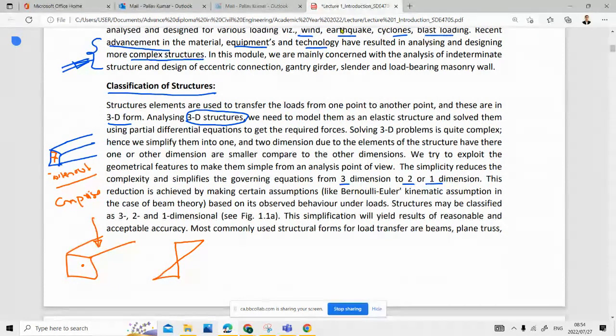Yeah, something like that. Yes, it's basically a stress diagram. Yes, it's an elastic stress diagram, and we assume that your material behaves in an elastic range. So that is what we do. And once we apply a load at the top, we assume that this form of shape will be there for the elastic stress. So the top will be in compression, because this is compressive stress, right? And the bottom will be in tensile stress. And if we talk about the central portion, we say that there should be zero stress at the center. This is what we assume, and we try to solve most of the problems in this way.